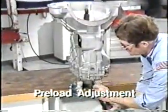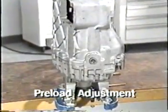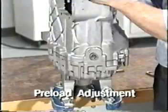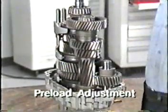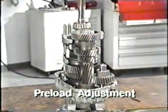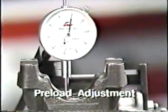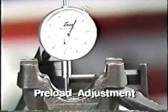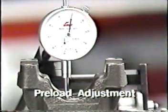Many transmission cases are made of an aluminum-magnesium alloy. Most subassemblies are made of steel. These metals expand at different rates. Preload adjustment compensates for the difference in expansion rates. Preloading the shafts makes sure the bearings fit correctly when the unit reaches operating temperature. Acceptable preload varies between a minimum and maximum. To adjust preload, shims are used to establish precise overall shaft lengths.